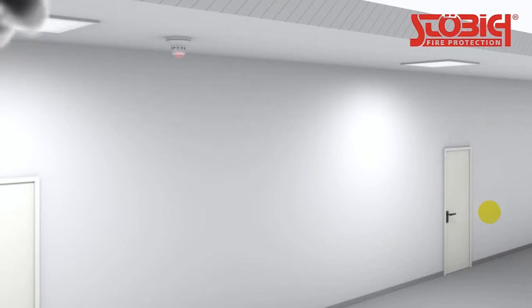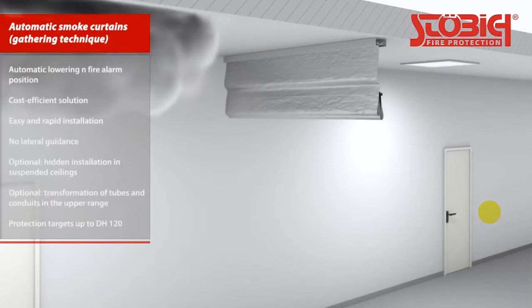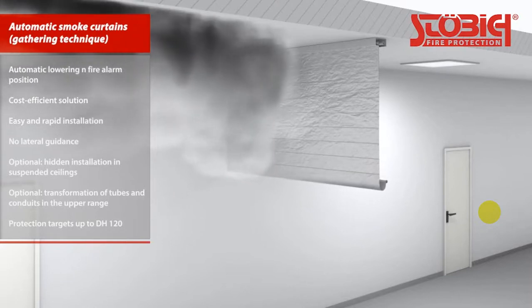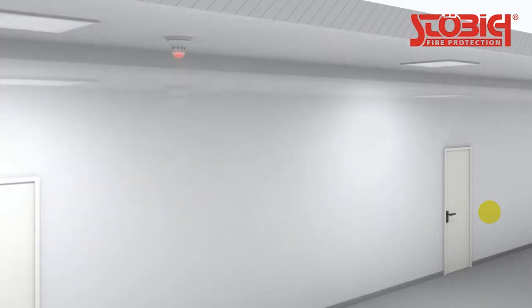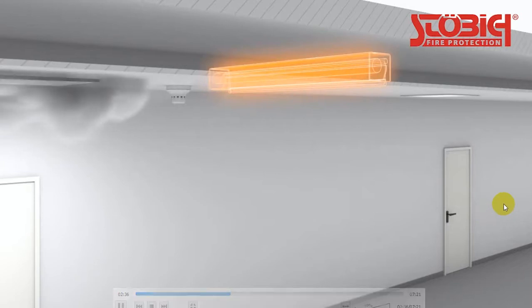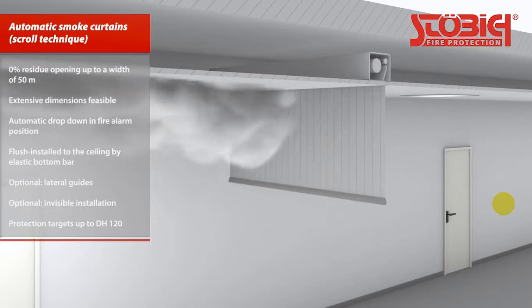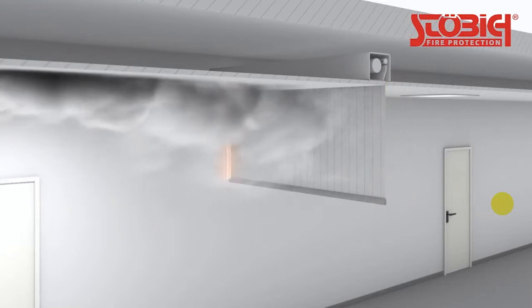Automatic fire curtains drop down only in case of a fire alarm to a specified room height. Gathered smoke curtains, for example, are suitable here. The textile is parked in a compact space above the ceiling and extends only when needed in case of a fire alarm. Automatic smoke curtains can also be rolled up and concealed in nearly any architectural space. They unroll to their in-use position only in case of a fire alarm. In this case, it is important to compensate for lateral leakage. Guide tracks are available for this purpose.